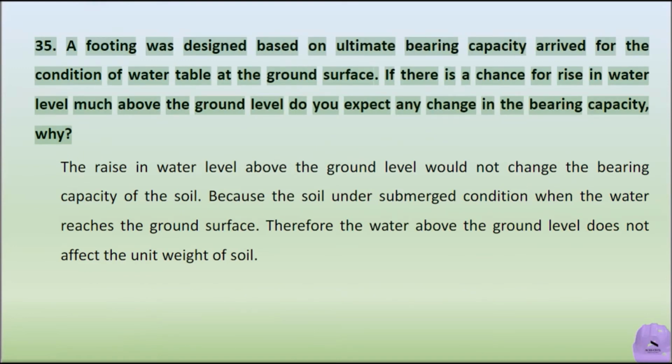A footing was designed based on ultimate bearing capacity arrived for the condition of water table at the ground surface. If there is a chance for rise in water level much above the ground level, do you expect any change in the bearing capacity? Why?